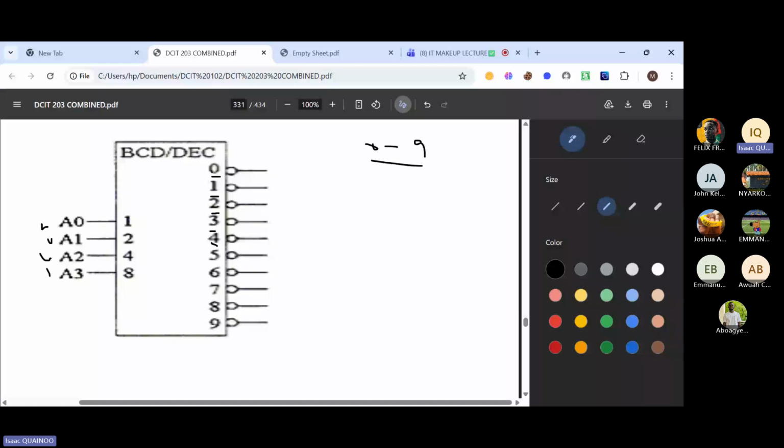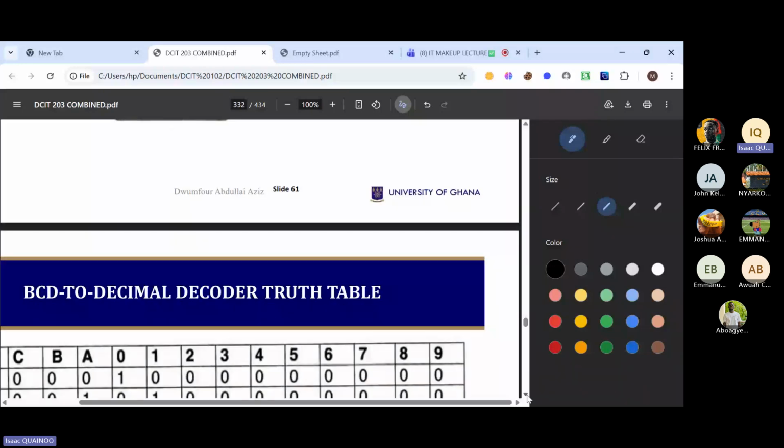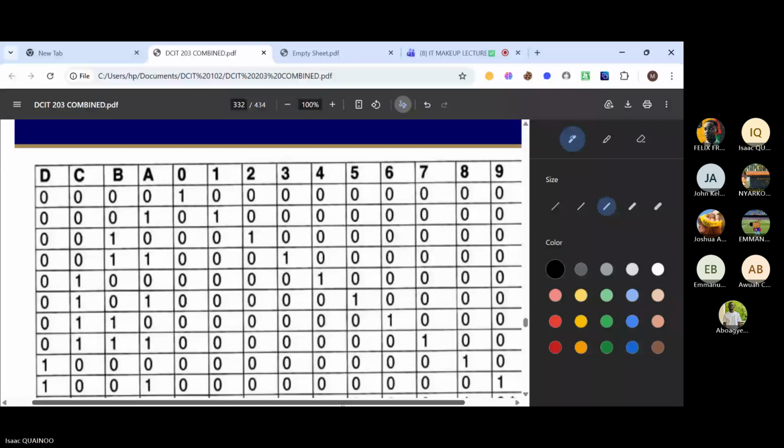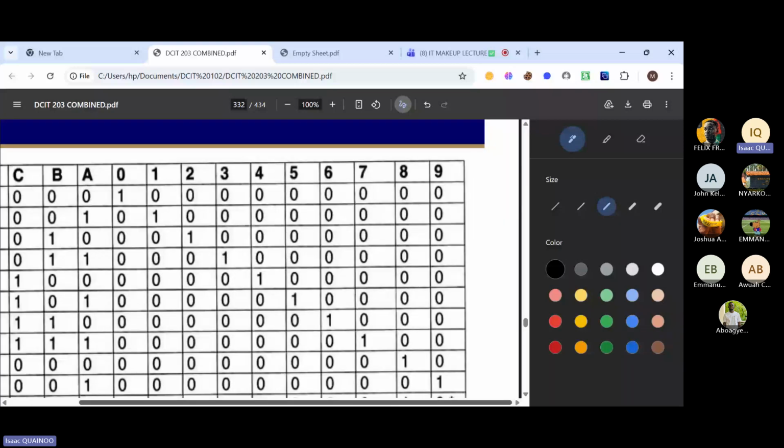So that is that for it. I wouldn't stress much on this since you've already spoken about that. So it has 4 inputs and then 9 outputs because the decimals have 9 unique digits, and there's a corresponding truth table. Our input is going to be our 4 inputs, which is A, B, C, D. Okay, and then our output is going to be from 1 to 9.